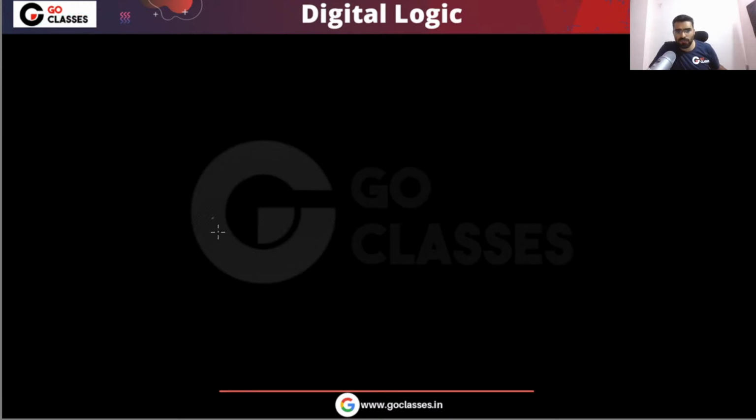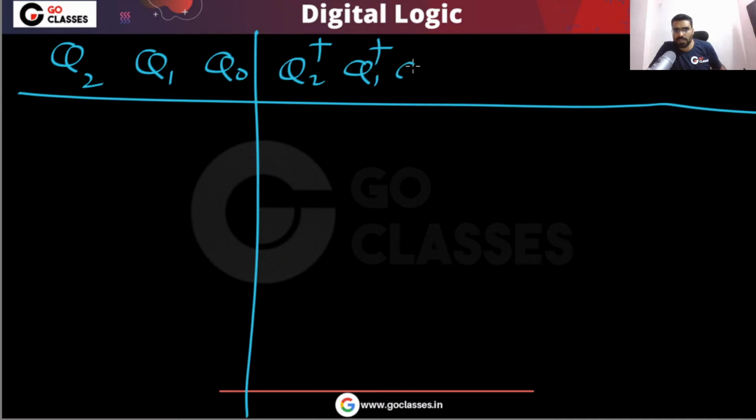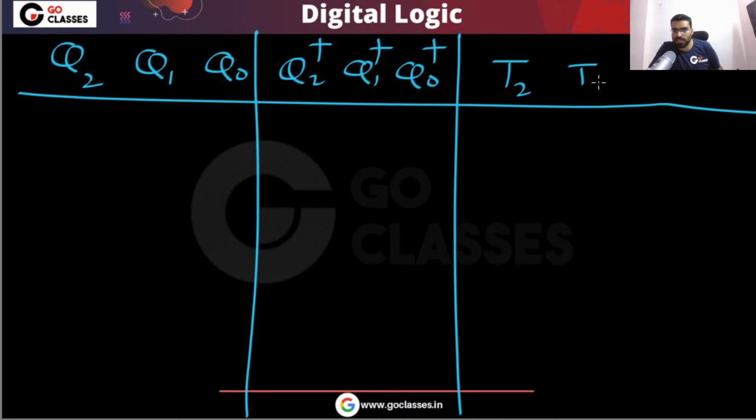Remember, there are 3 flip-flops. So your current state will be Q2, Q1, Q0. This is your current state. And your next state will be Q2 plus, Q1 plus, Q0 plus. And there are 3 T flip-flops, T2, T1, T0. Now you can notice this T0 is fixed equal to 1.